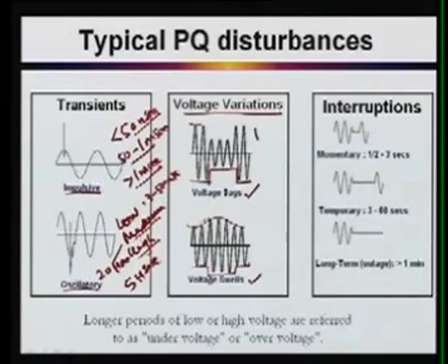Here the voltage dip, this magnitude, how much dip? If your voltage here is between 0.1 to 0.9 per unit, then it is called voltage dip. Here, why is it 0.1? If this is less than 0.1, then it is called an interruption, because of a sudden short circuit, the voltage is almost 0. 0.9 we have mentioned because a voltage of more than 0.9 per unit is sometimes known as the normal voltage.